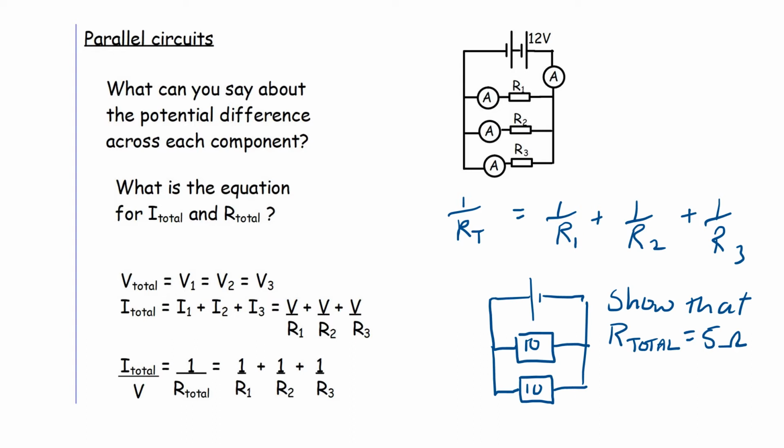So we know that when we combine resistors together in parallel, the total resistance decreases. When we're talking about the total resistance, we're really thinking about the effect of those two resistors together in the circuit, and thinking that we could replace those two resistors with a single resistor which would have the same effect.